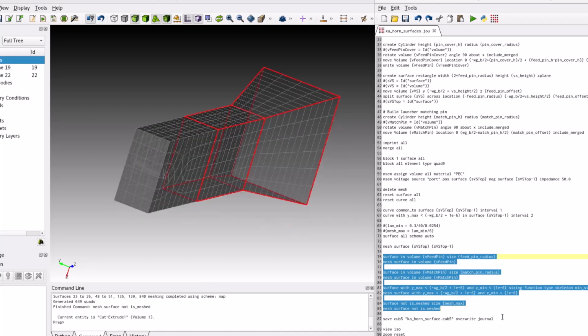Now that the mesh is complete, it is helpful to perform an assessment of the mesh quality. A mesh quality of 1 represents a perfectly square quad element. A mesh quality of 0 means that 1 or more quads are malformed, and further mesh diagnostics are required.